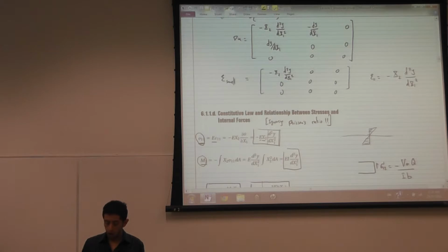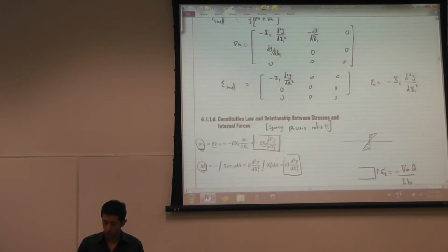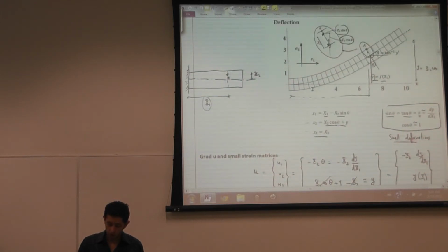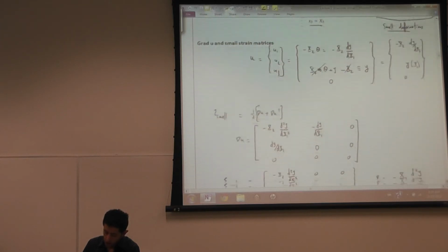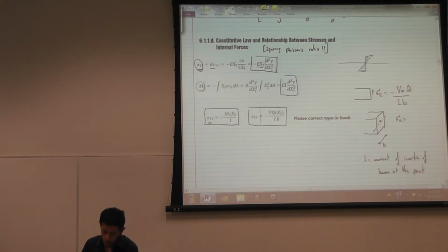But for all the beams that you're actually analyzing, you're saying there is shear stress, but there's no associated shear strain. So why is there no shear strain? Of course, in this system, it's all because of the assumption of plane sections remaining plane and perpendicular. Because of this assumption, when I consider this coordinate system E1 and E2, there's no shear strain in this coordinate system because these always stay perpendicular. Yet there is shear stress, and the shear stress is calculated using this formula. Sigma 1, 2 is equal to negative VQ divided by IB.